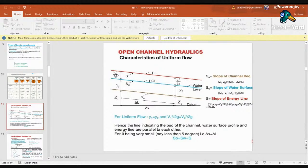Then your V1 square by 2g is the energy line for the given water surface. Okay, here we have assumed that S is the slope of energy line, Sw is the slope of water line, and S0 is the slope of channel bed.